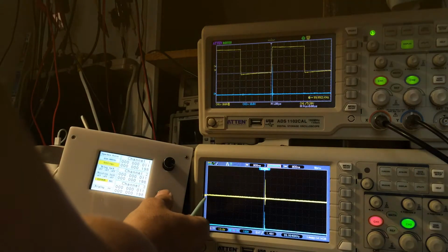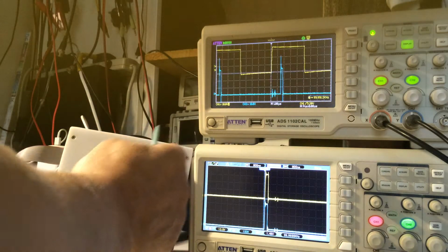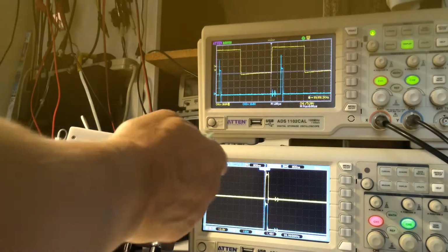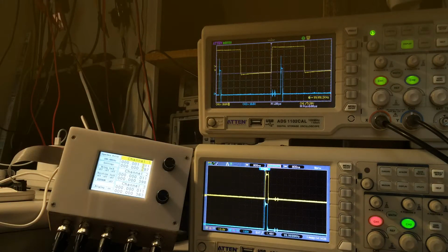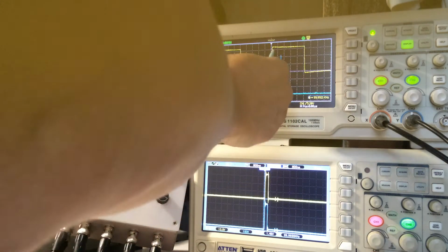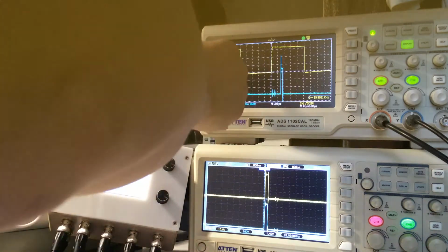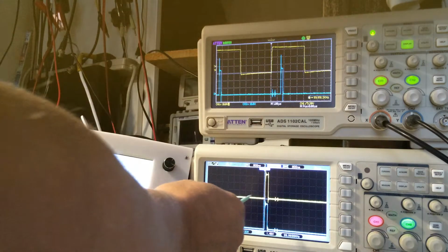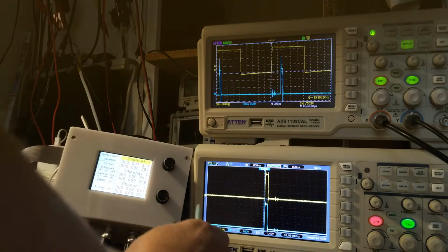Let's see the working of my device as an example of one channel only first. You can see the top oscilloscope. Every channel of our device produces a pulse sequence. This sequence has two main parameters. First is just a delay of the front of the output signal after the front of the synchronized pulse. It means this is the distance between the edge of the synchro pulse and the start of the output signal.